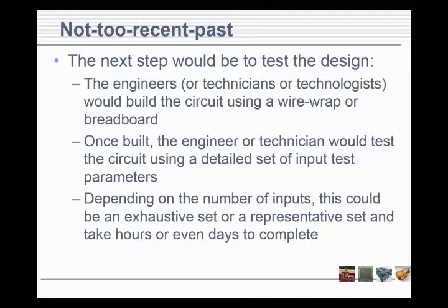Now this was really tricky, because you had to press it with enough force that the coils you were wrapping around that post, or that pin, would stay right next to each other, because you didn't want them all stretched out. It would take up too much room on the post. You didn't want to push too hard, because then they would be kind of all bunched up over each other, and that wasn't right either. So you had to learn to put just enough force on to make it look real nice and neat. And you had to cut the wire to the point where it would only have like 3 or 4 wraps, because you didn't want to be able to pull it off.